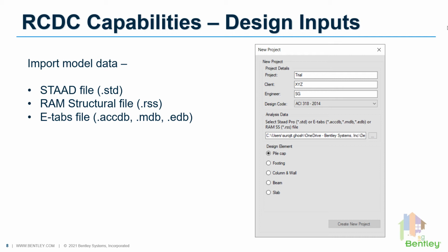Note that RCDC imports the member and plate information along with the design forces from the structural model. There is no separate analysis engine available in this module. So you must analyze your structure first before importing it to RCDC.